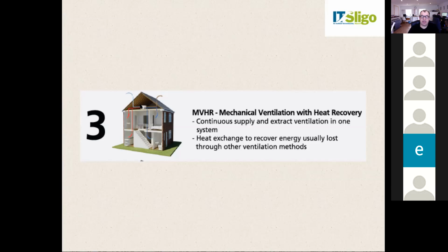It's mixing the two together separately, and it's pushing warm, pure air into the rooms that need it, such as the bedrooms and the living rooms. And that's the heat recovery that's going on in order to make sure that the rooms are at the right temperature. This is the system that the Passive House Institute insists on. We're going to look in a moment at PHPP to show you the difference between having a system that's MVHR and not having it.